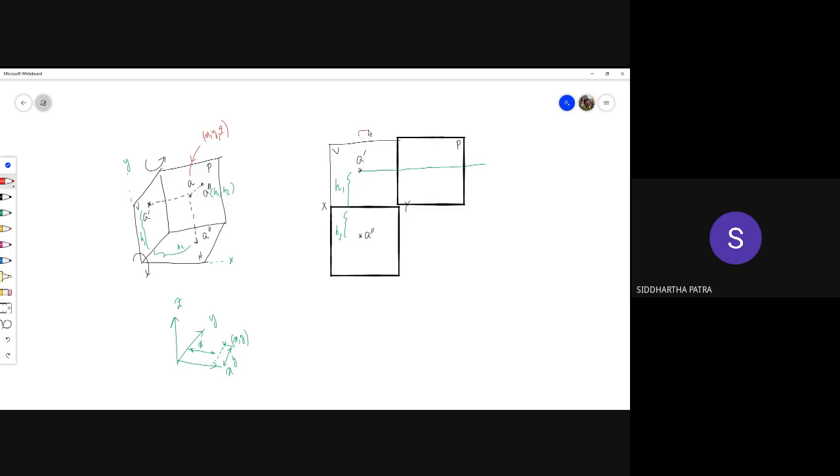The distance from the profile plane, let's call it h3, is going to be the same in both the vertical and horizontal plane. But the remaining values h1 and h2 are independent of one another, and those are the only two values that you need to plot the point on the profile plane.